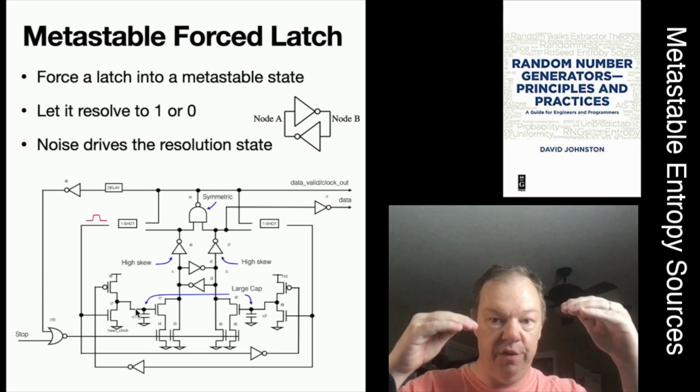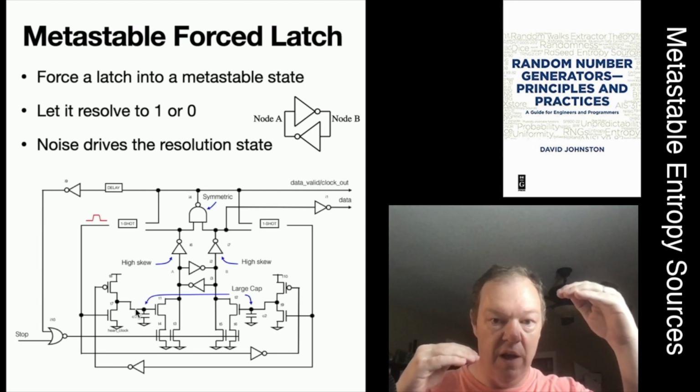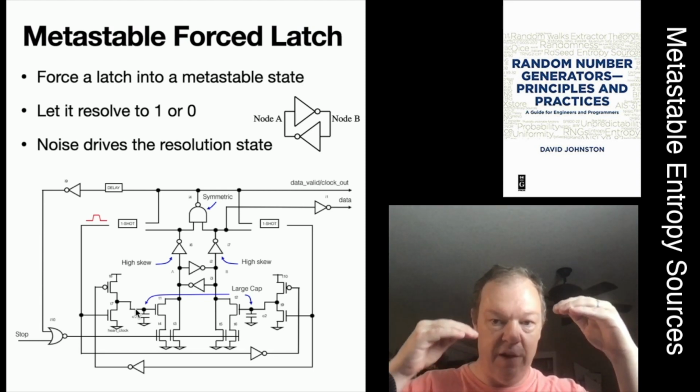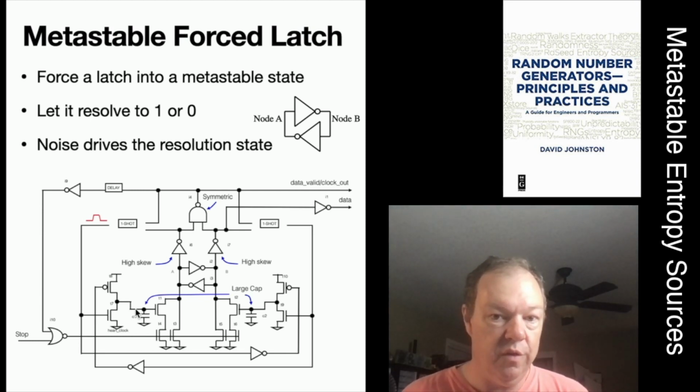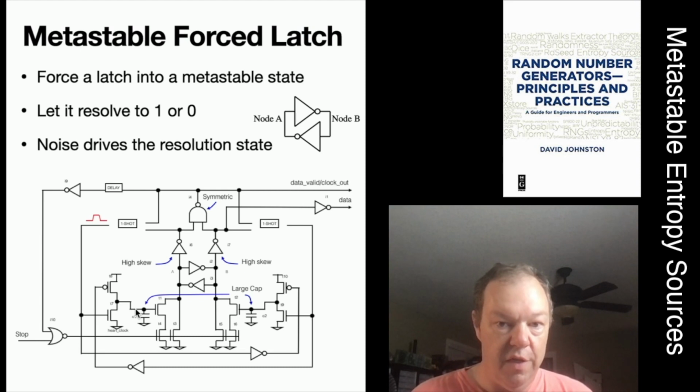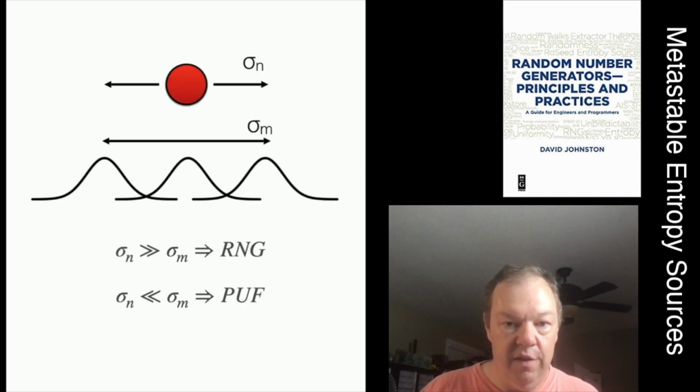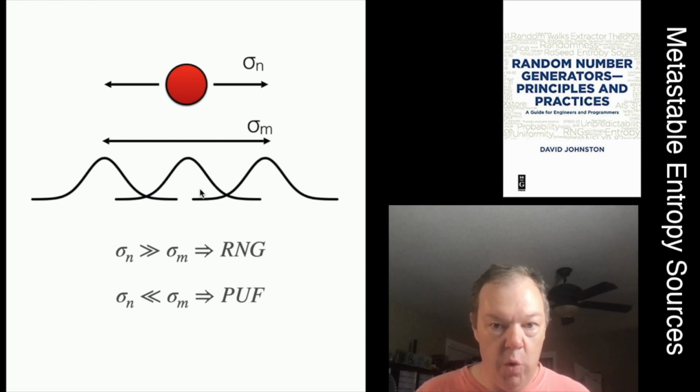If you get more 0s than 1s, it starts going in the other direction, pushing it to create more 1s. And so you've got this stabilizing thing that if you're getting too many 1s or 0s, it starts to produce more of the other value. And that, in effect, is pulling this hill into the middle. So we've got some manufacturing bias, and we're applying this load on the capacitors, a voltage, to load the circuit on one side or the other, to move the hill into the middle.